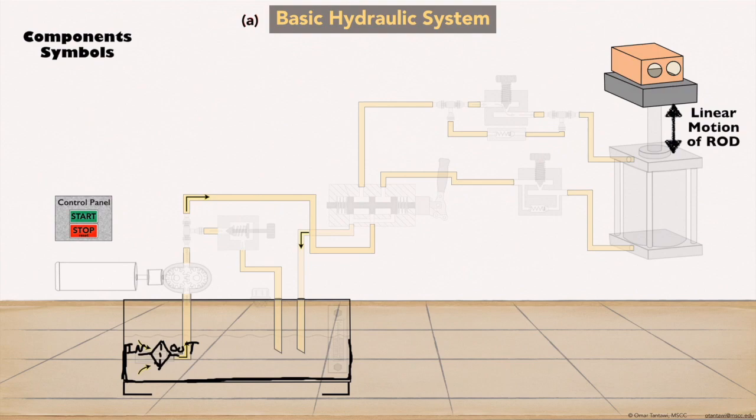And the filter will go to the pump. The pump is a rotary pump, so indicated by the circle. And a solid arrow, a solid head arrow pointed on the outlet of the pump, and that's indicating the pumping action that we've talked about before.